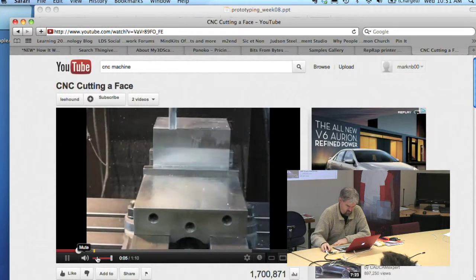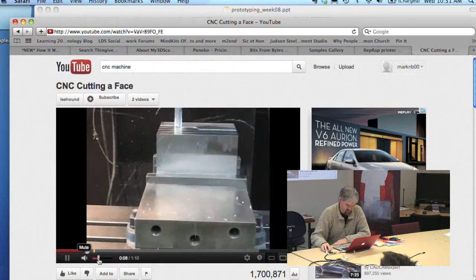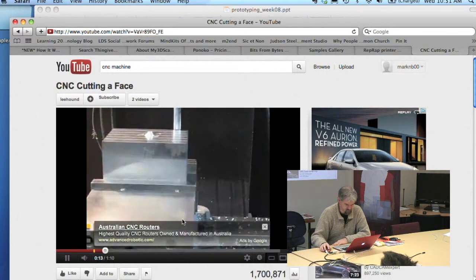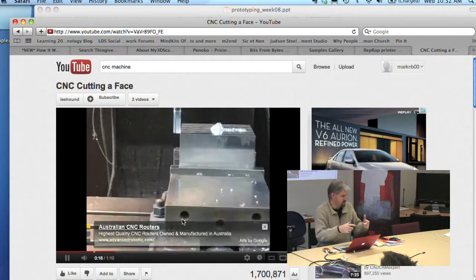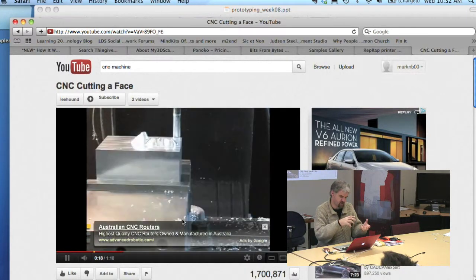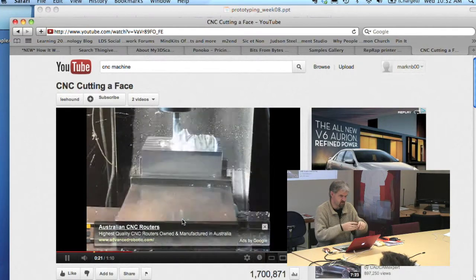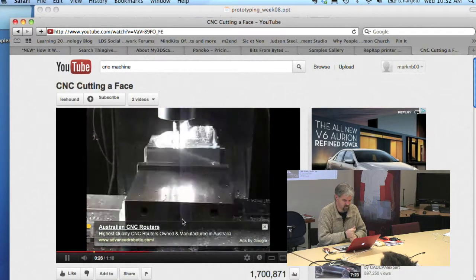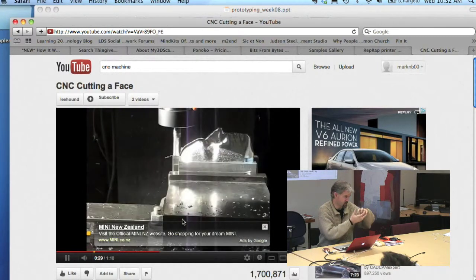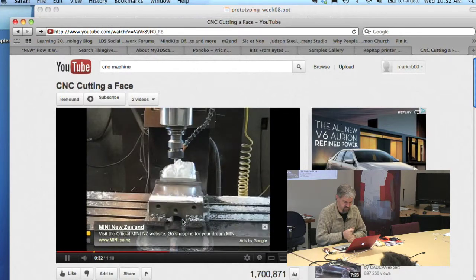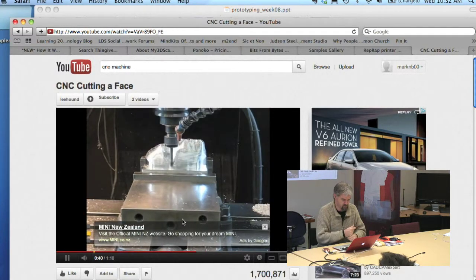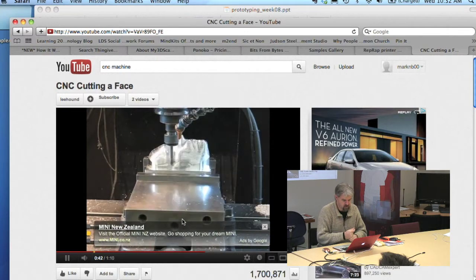So some really great Indian music. You can see there it's carving away. This is the carving head right here. And of course, because it's carving, it means that you can't necessarily create completely hollow objects. With stereolithography, you could print a hollow ball, but with CNC you couldn't do that. You could just produce two halves of the ball and then glue them together. So they're making a face here. But the good thing about the CNC machine, and there it's finished, is that you can carve quite hard materials. This is the metal that's carving right here. You can do wood and things like that as well.